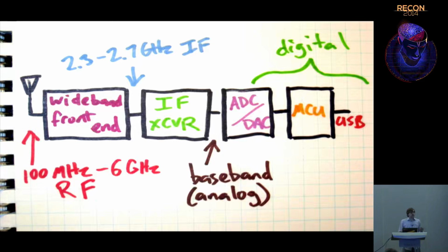So we can tune to the sum of 5.4 gigahertz and 2.75 gigahertz, which is about 8.15 gigahertz, much higher than the advertised operating range of the HackRF. So let's just try that and see what we get.